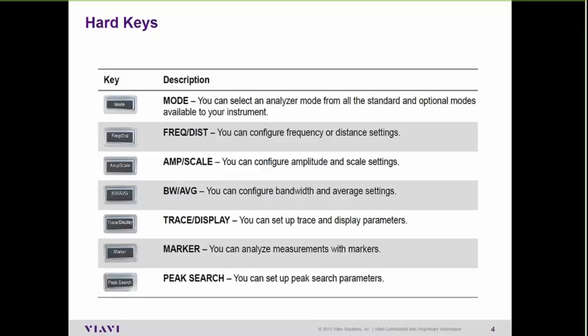You can also use the bandwidth or averaging key. And so this allows you to improve the noise floor measurements. So with any spectrum analyzer or channel power measurement, there is the capability to reduce the resolution bandwidth. And the smaller the resolution bandwidth, the finer you separate the various blocks across the screen as you're measuring power, the more accurate your spectrum analyzer power measurements will be.